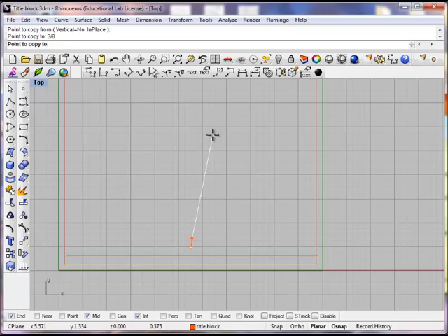Now we want to go directly up, or straight up 90 degrees. So I'm going to hold my shift, and what it'll do is it'll snap to that 90. It'll also snap horizontally, which we don't want, or down, in any 90 degrees. We're going to hold that snap, and no matter how far away, I can left click, and it places that line there.